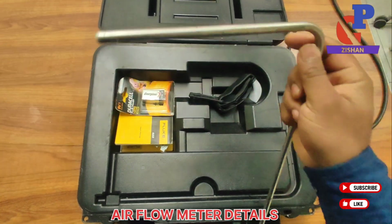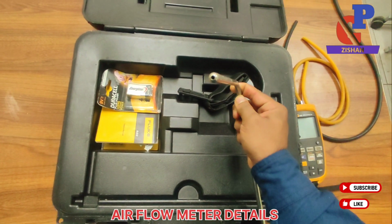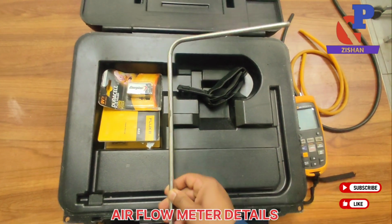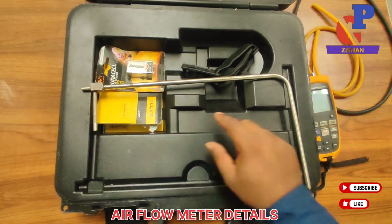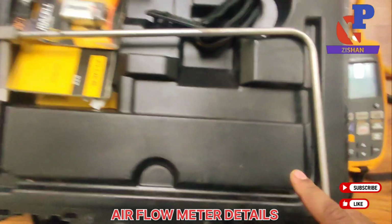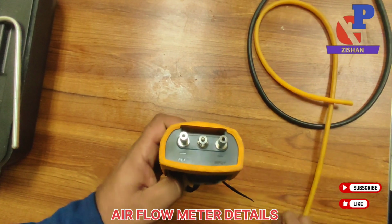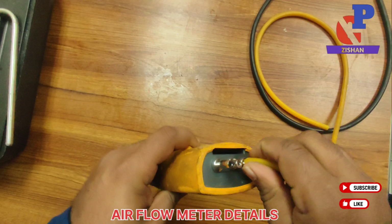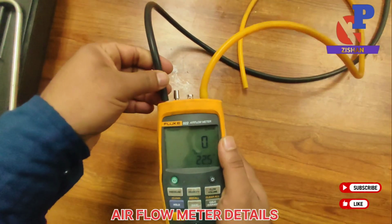This hole gives you the static pressure, and that is connected to the device. This is the main hose. This one is for the static pressure, and another one is for the dynamic pressure from inside the duct. It gives you the dynamic pressure. Now we are going to connect the yellow hose to the positive pressure side, and the black hose to the negative pressure side.